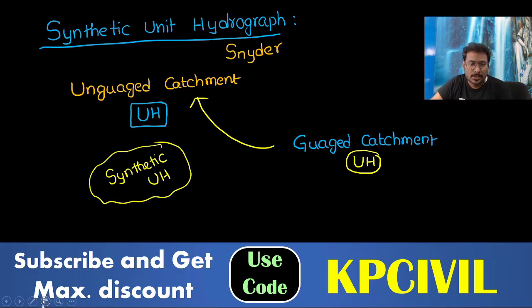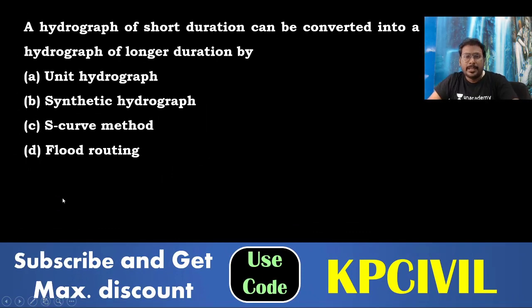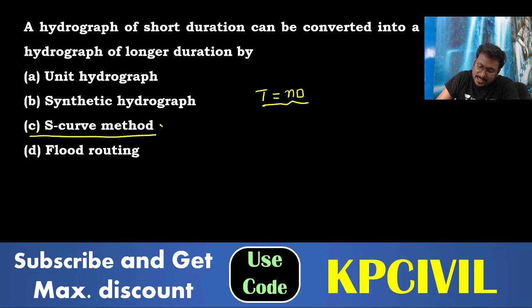Clear? So we'll go on to solve some objective questions. A hydrograph of short duration can be converted into a hydrograph of longer duration. No relation is mentioned; they have not given T equal to ND or anything like that. What can we follow? Nothing is given, so you go for the S curve method. You can plot any kind of hydrograph, any time, any depth, whatever it may be. You always plot using the S curve method.